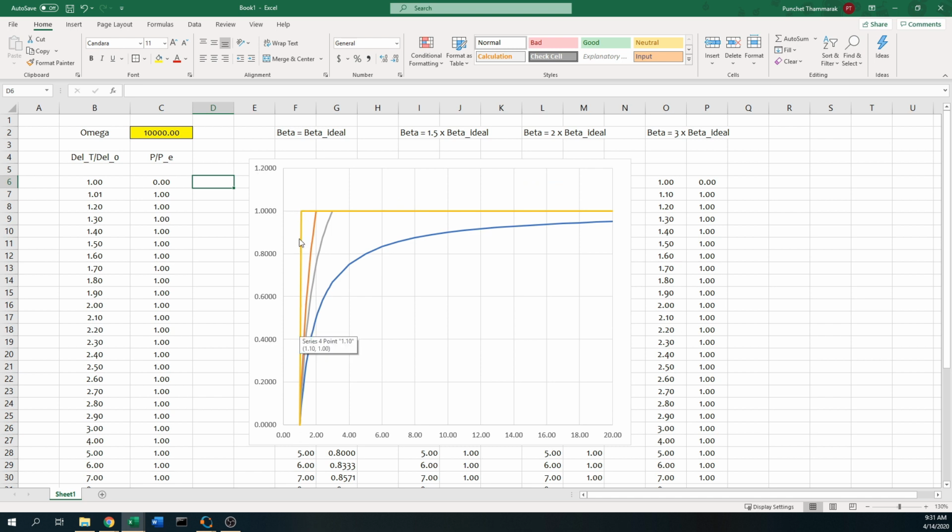So this is the best that you can get, the yellow line. The graph just goes like a straight line from this point, which is very expensive. To move from the point somewhere around here to here, it is infinite. So you will need the ideal brace stiffness to be somewhere around just 2 times or 3 times, and that will be enough for the purpose of bracing the system in order to go all the way to the full buckling load.